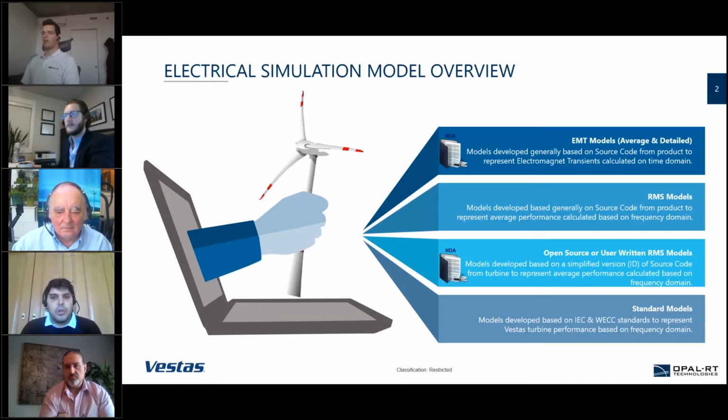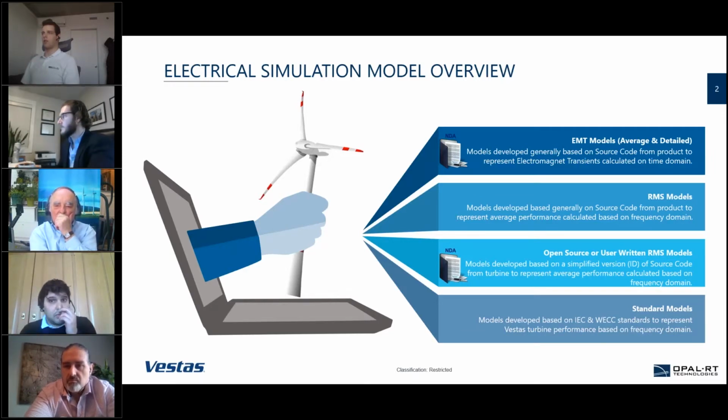So first, to place ourselves in the different available models we have in the market from different OEMs, we could group them into four main ones, right? The first of them will be the EMT models. We have talked a lot about EMT models, but we have to make sure that it's not only the control part and the source code integration or the digital twin that takes part in regards to the control, but also the way to model the hardware. And this is something important that we need to keep in mind. When we talk about EMT models, different OEMs might choose one or another approach that implement average or detailed representation of the inverters, and that will make a huge difference depending on the type of phenomena you are analyzing.